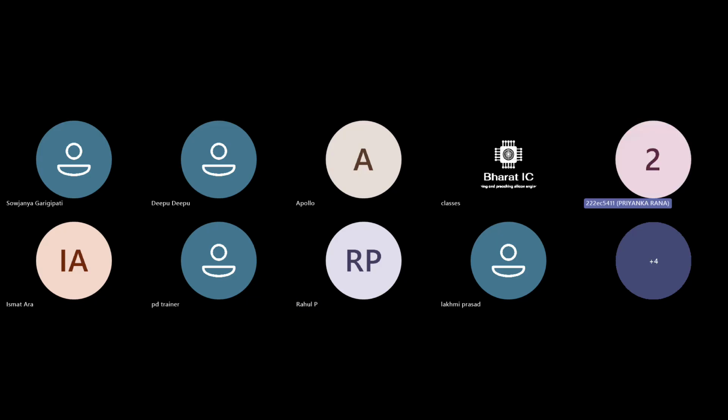Like in macros, if there are so many pins, can we keep it at the edges of the core? Yes, we can keep them, but again, it depends on the connection. If they are having more connections with the IO ports, then we'll keep it at the edges, and we will tilt the macro in such a way that those connections face the outward side of the core area.